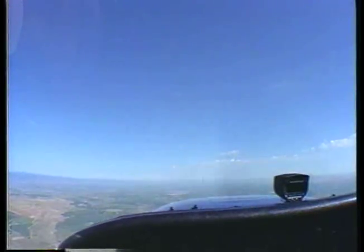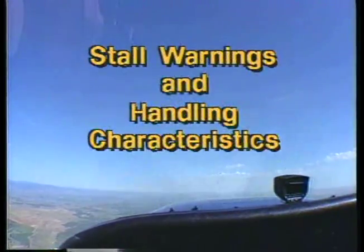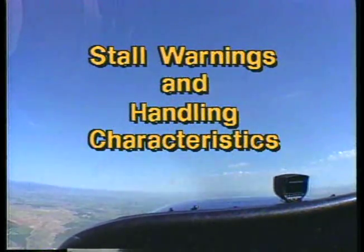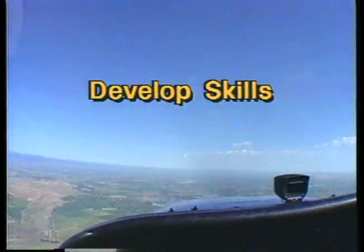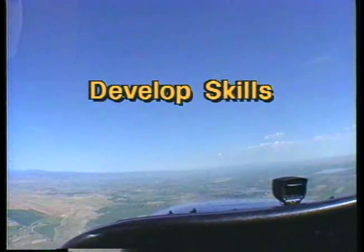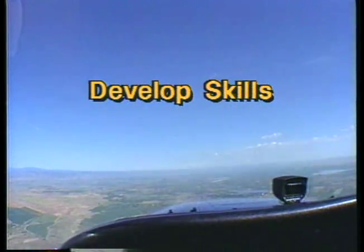You practice stalls for two reasons. First, they acquaint you with the stall warnings and handling characteristics of your airplane as it approaches a stall. And second, they develop your skills so you can recover from an inadvertent stall quickly and efficiently with a minimal loss of altitude.